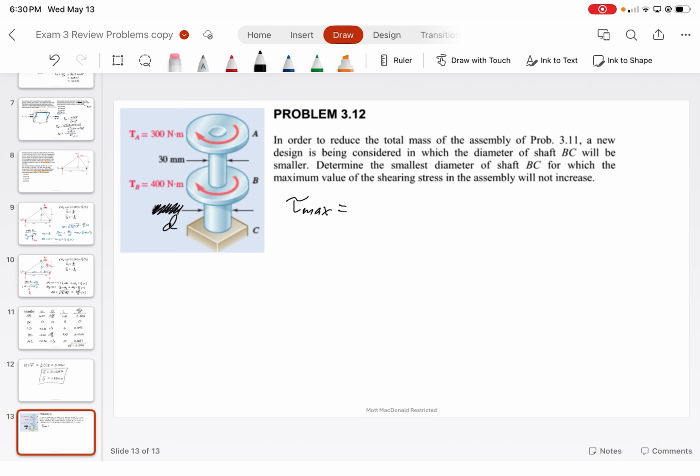Yeah, you need a maximum shear stress. So let's say that's, I don't know. What's a good example? Is this from the textbook? Do you want me to go check and see if it's given? No, we could just assume something, because then the maximum shear stress would just change accordingly. So if it's type A992 steel, it's just going to be roughly 60% of that. So that's about tau max equaling 30 KSI. Let's say I want to use a factor of safety of 2, which means that the allowable stress is 15 KSI. All right, so that's what I want to use for this case.